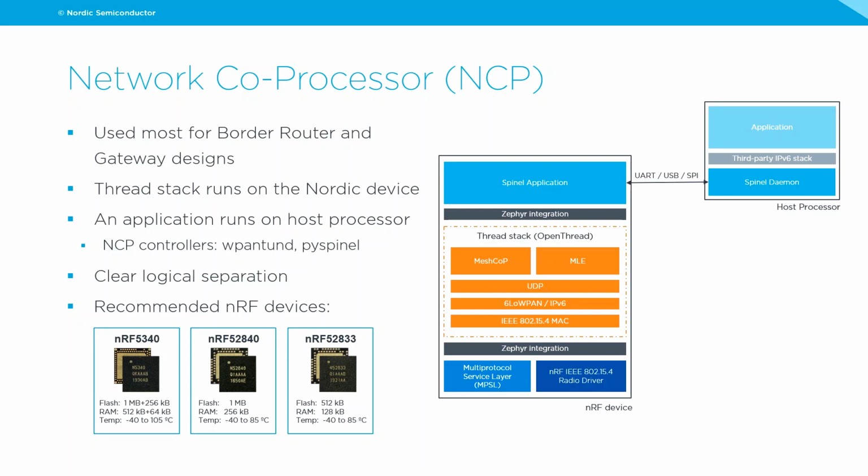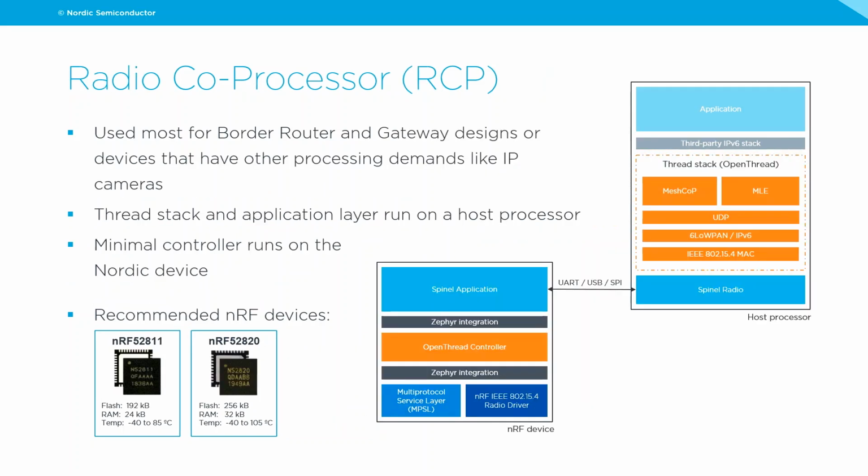One of the key features is that the higher power host can sleep, while the lower power Thread device remains active in the Thread network. And finally, here you don't need to have the dual bank DFU or external flash, since you may incorporate a serial bootloader into the NCP and perform DFU from the host.